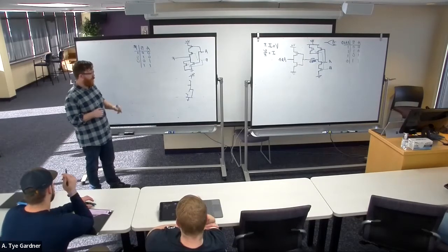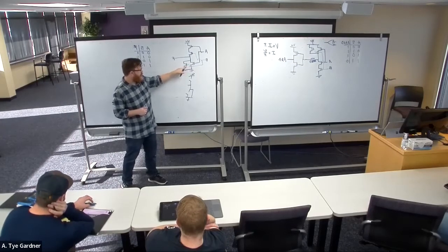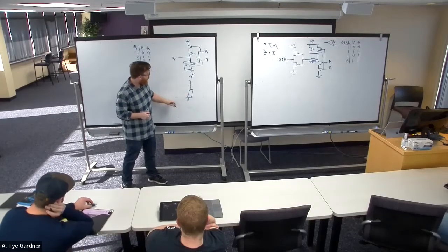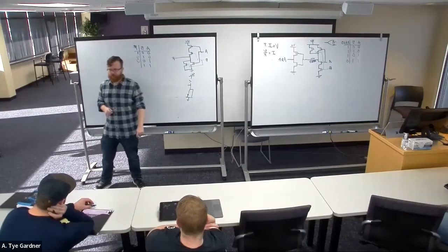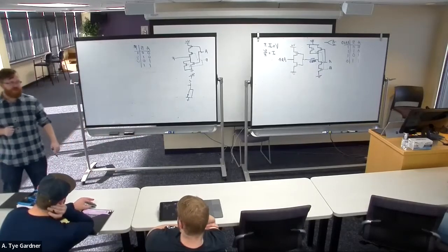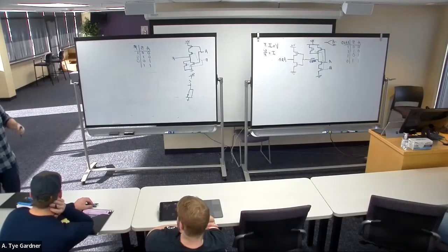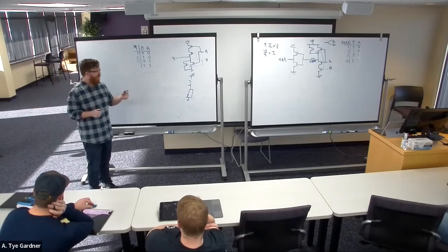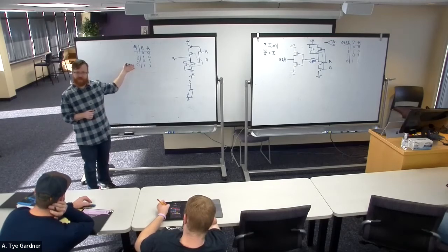Now all I have to do is go, what happens in the 1 1 case? Well, on the bottom side, 1 and 1 means they're now both closed. And on the top, they're now both open. Well, I've doubled up the situation where I doubly can't get the VCC. Doesn't really matter. And I can twice as easily maybe get to ground, kind of, but there's no resistance. So it's twice as easy as 0 is still 0. And so I get 0. What did I build? NOR gate.